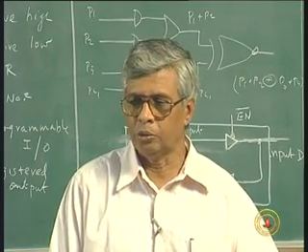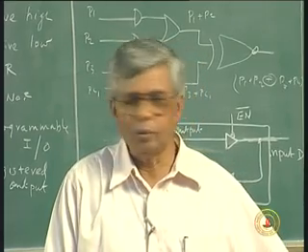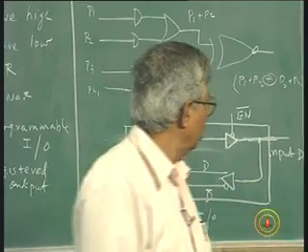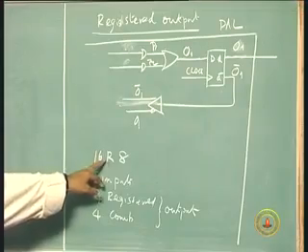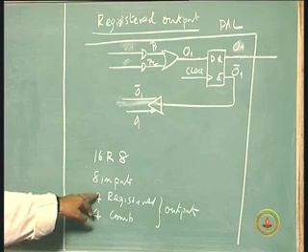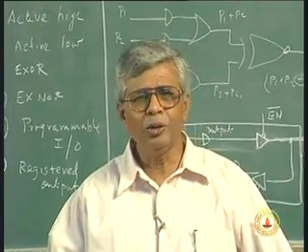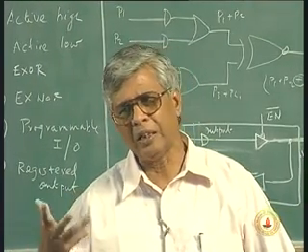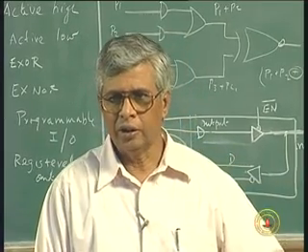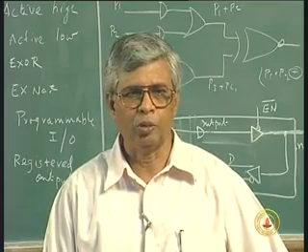I told you programmable array logic is more popular. We usually consider 4 or 5 or 8 inputs, for example 16L8 as an example, 16R4 is another example. 16R4 will be 8 inputs, 4 registered outputs and 4 non-registered outputs. Now, these are all right for many problems that you do in the class, and also many small systems like elevator control. You go to a lift, the control is a logic circuit in which there may not be more than this number of inputs and outputs.